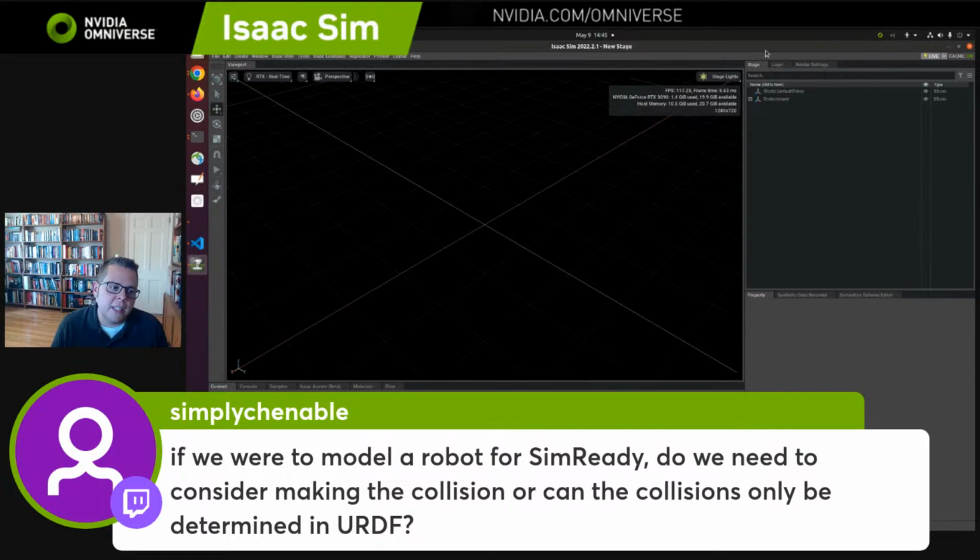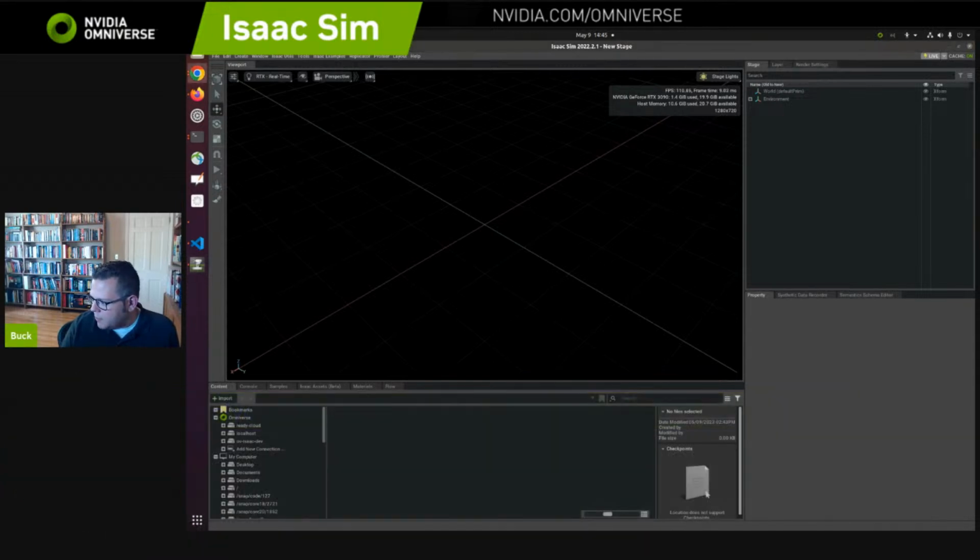And then if you want to avoid collisions, either by planning a path offline using the global planner in Lula or using RMP flow, you do need the collision spheres I mentioned. Those also live in the robot description file, just as a list of spheres. And I could show you how to produce a robot description file, but I'll suggest you hop back to the live stream from 2 weeks ago. That's linked in the chat. And you can skim through Avi's live stream to get to the point where you see him adding big yellow spheres to a robot. That's the part you want to watch. And that goes through the process of adding these collision spheres. I'm going to assume that that's what was meant by the question, but let me know if not.